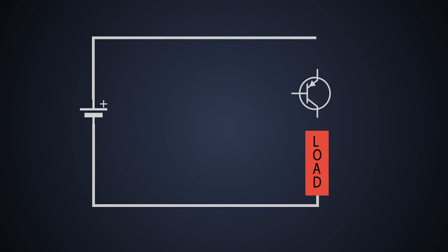We'll connect a PNP BJT in series with the load and supply so that it cuts off the supply when the voltage exceeds. Basically, it will act like a switch. We'll name this transistor Q2. We'll connect one resistor R2 from ground to the base of the BJT. This resistor will pull down the base of the BJT to the ground so that it stays on all the time and current flows to the circuit whenever supply is given.